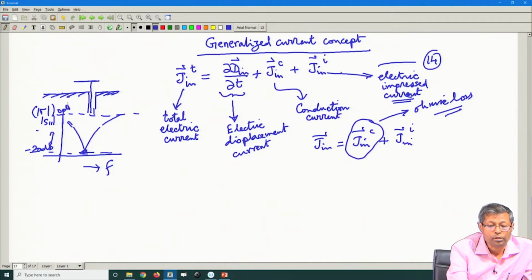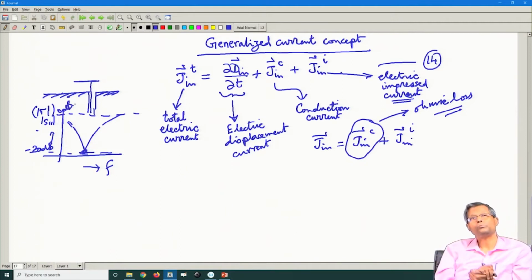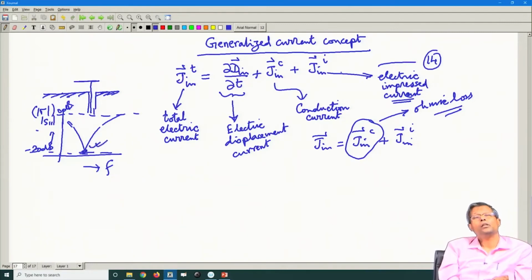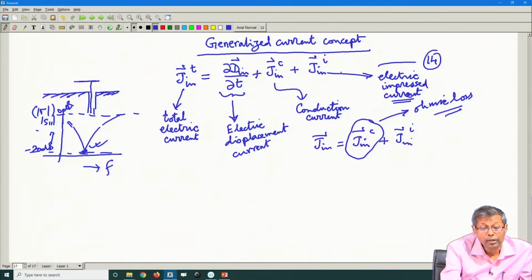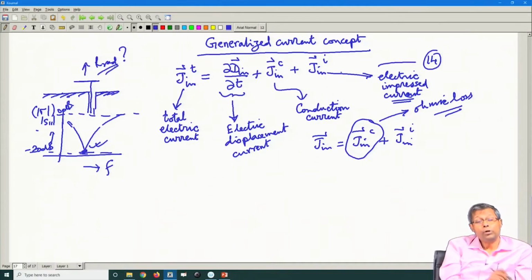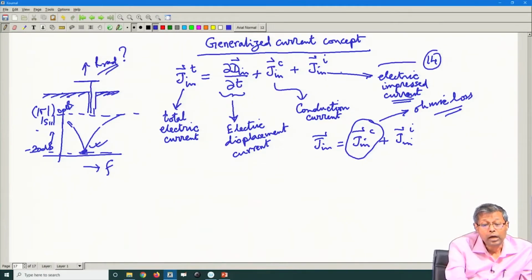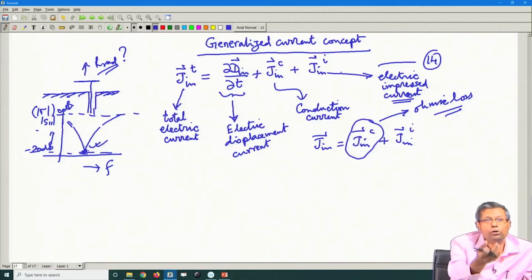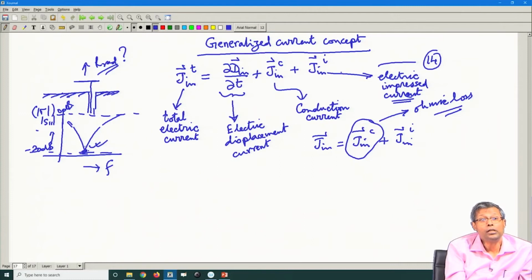So, this is 0 dB. At this point you might imagine that we are getting a very good match to the antenna. That is fine, you are indeed getting a very good match, but it does not mean that this antenna is radiating. Why? Because it means that somebody is absorbing power from you. The power is not reflected back at you, but who is that somebody?